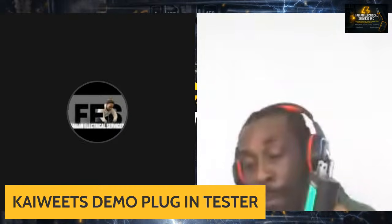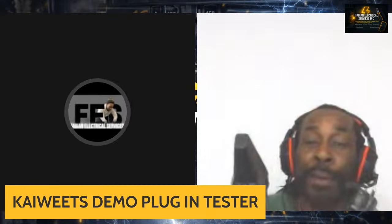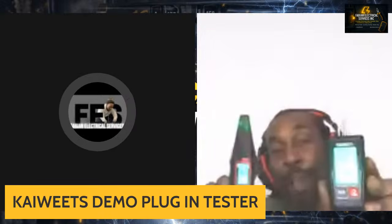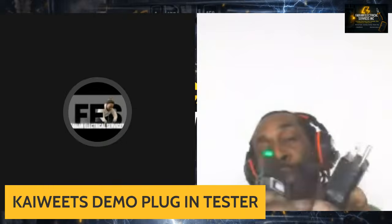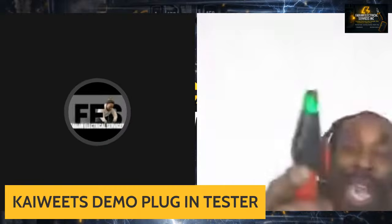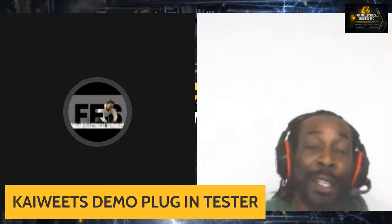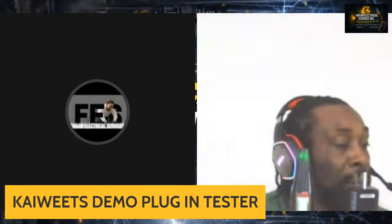And you also have the scanner. So this is the scanner, and this is basically how this works. You have the transmitter here, you have the scanner. This goes into the outlet. Once you press the on, you're going to see a signal going around here, like a Wi-Fi signal. You're going to scan this down your panel onto your wires. Once this turns red, that's telling you that's the cable that you need. So this is how I go about using this and saving time on the job site.